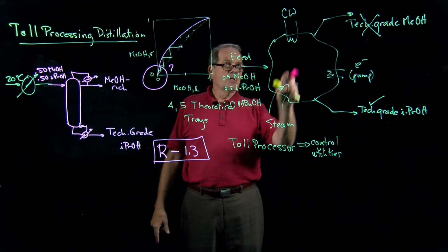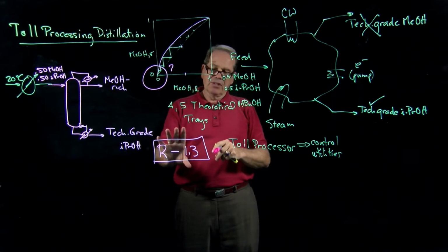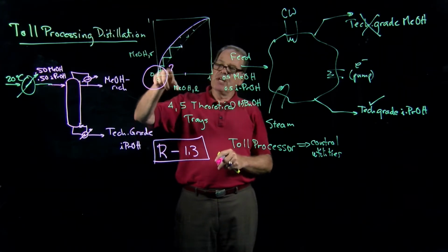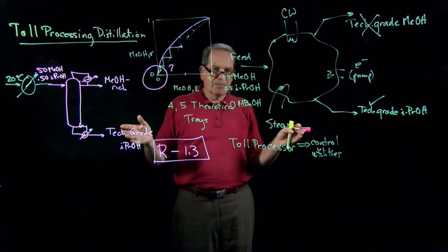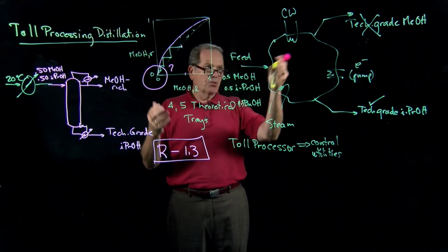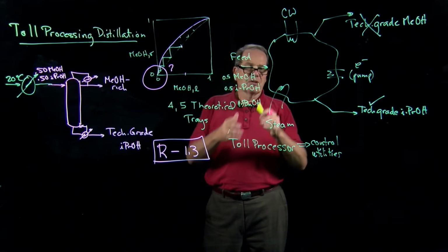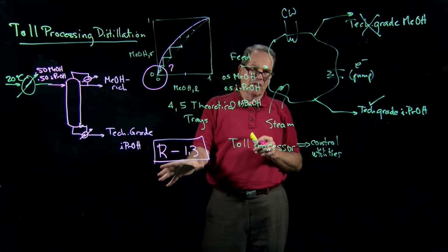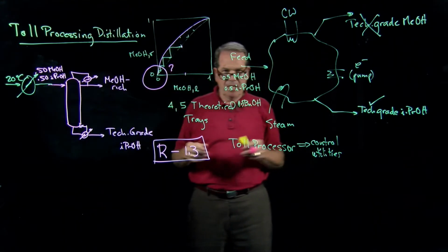I'm going to use a lot more steam. I'm going to use a lot more cooling water. And so I'd rather not raise this reflux ratio very much if I can avoid it. I probably can't go too much below this because if I'm trying to reach a very tough target and I have any process upset, like a change in temperature, or I lose cooling water for a while, or the steam line gets clogged, or the valve freezes, and I'm at a very low reflux ratio, then I'll get very fast fluctuations in the column operation. The dynamics are not what we need.